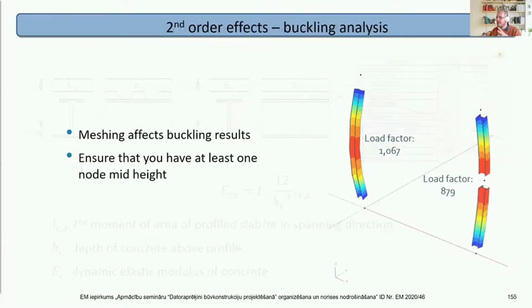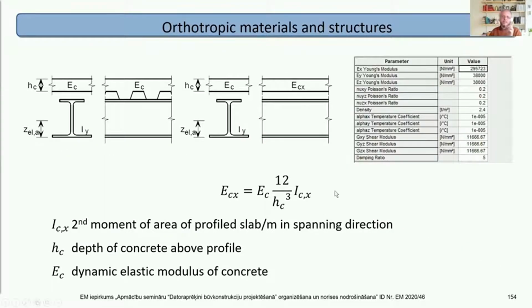I also will say something about the loading duration for the concrete. See, the Young's modulus for the concrete is actually quite a lot higher than the normal version. So this for vibration will be the dynamic modulus of concrete rather than the short-term modulus. So concrete stiffness under low strain vibration is quite high. Obviously, getting to seismic, it starts breaking and everything, different matter. But yeah, general serviceability of a vibration, quite a high stiffness in the concrete.